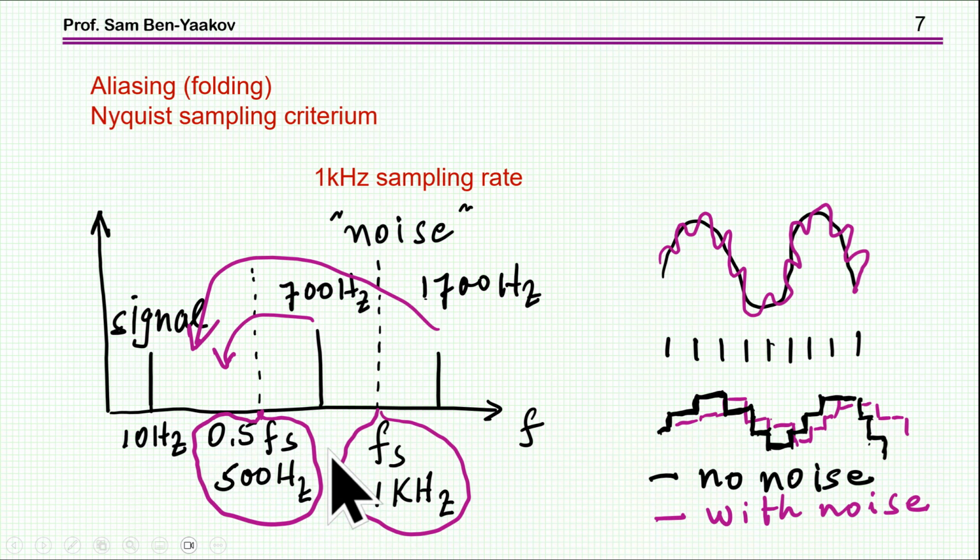To understand what is the problem, I've sort of scribbled down here a signal with some noise to it. And the noise is close to the sampling frequency. This is supposed to show the sampling instances, okay? So as I sample it, without the noise, I'm reconstructing this staircase type of waveform. This will be on the sample and hold capacitor. But with the sampling, I'm starting to sample the noise at different points, which actually gives rise to a frequency which is lower than the noise frequency. And this is what we call the folding.